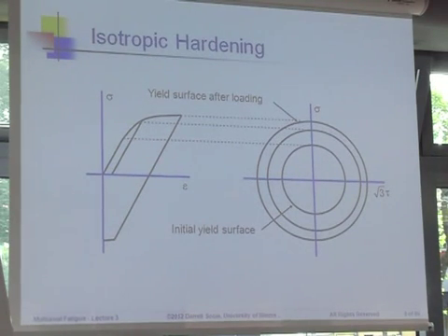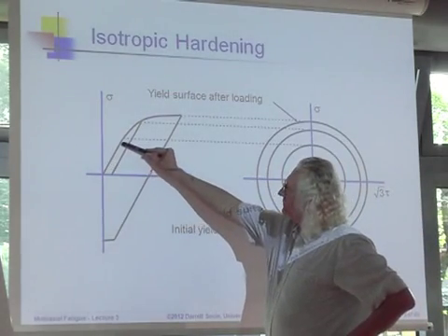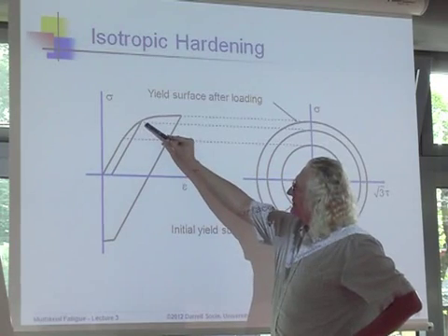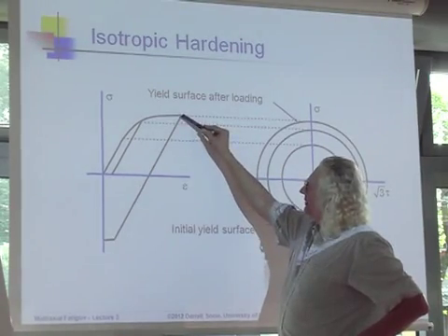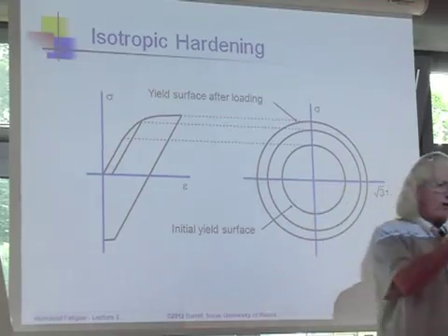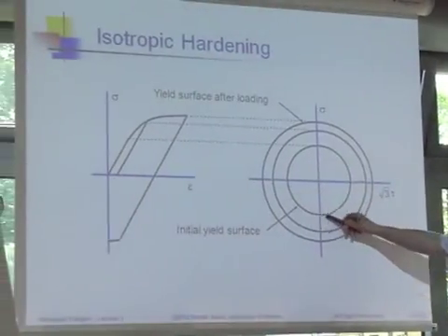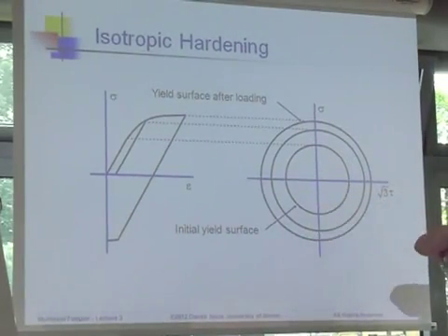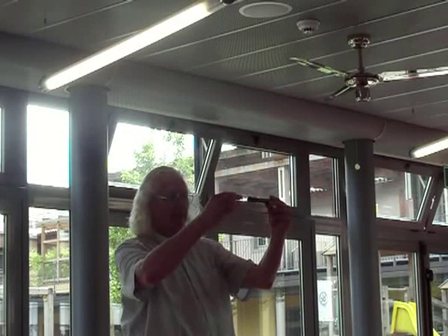And now I already mentioned isotropic hardening, but let's look and see what happens. When I isotropically harden something and deform it, I load it like this, and if I unload it and reload it, the strength gets bigger, and if I reload it again, the strength gets a little bigger, and if I unload it, I'll get a path like that. And if I look now at what's happening in 3 dimensions, that essentially takes these yield surfaces, and again I'm just going to use the 2-dimensional version because it's easy to point to. What that says is that I'm going to load this, and maybe I have an original yield strength of 10. And I plastically deform this to a stress of 20.